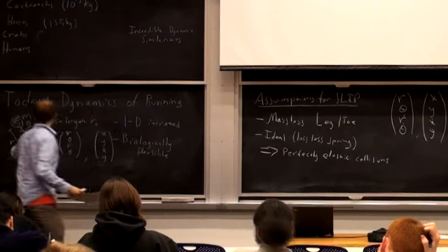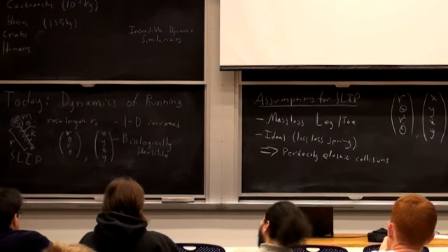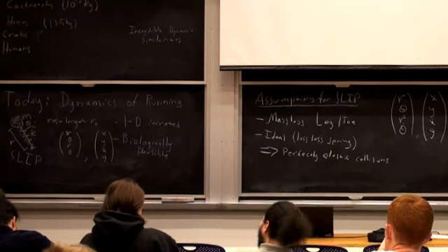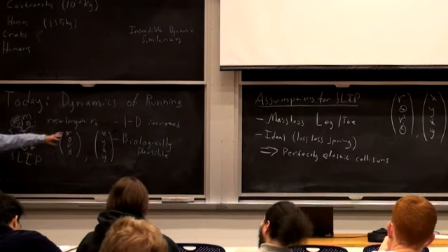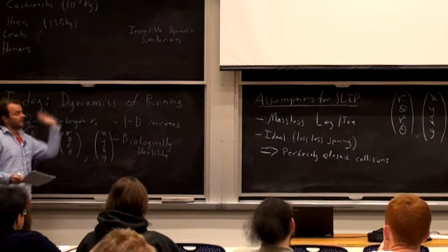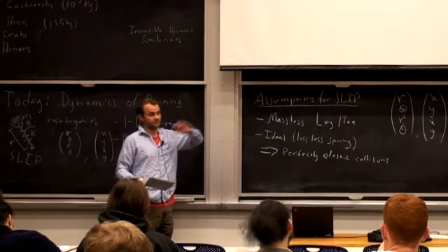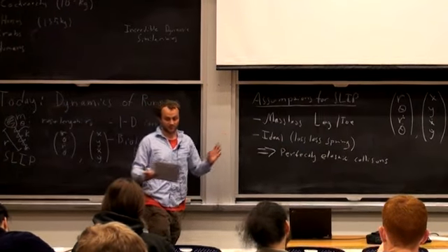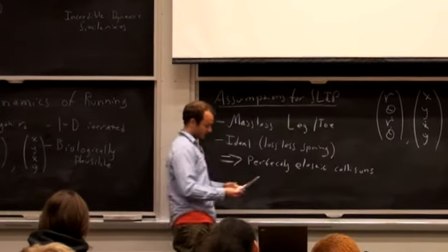When it hits, even though the toe sticks in right away, in a kind of inelastic collision, because there's no mass there, there's no energy and no momentum in it. You don't lose any energy, and so it's actually conservative as it runs through. And flying through the air, there's no drag or anything, it's conservative when it flies through the air as well. And so this system is completely conservative in its full operation. So it's very different than a rimless wheel.